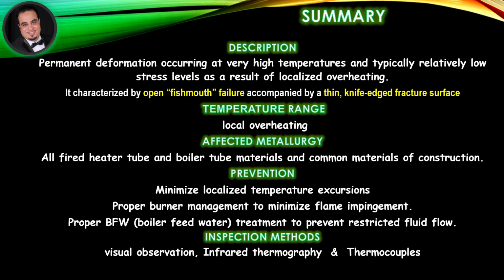Temperature range. Local overheating. Affected metallurgy. All fired heater tube and boiler tube materials and common materials of construction. Prevention. Minimize localized temperature excursions. Proper burner management to minimize flame impingement. Proper boiler feed water treatment to prevent restricted fluid flow. Inspection methods. Visual observation, infrared thermography and thermocouples.